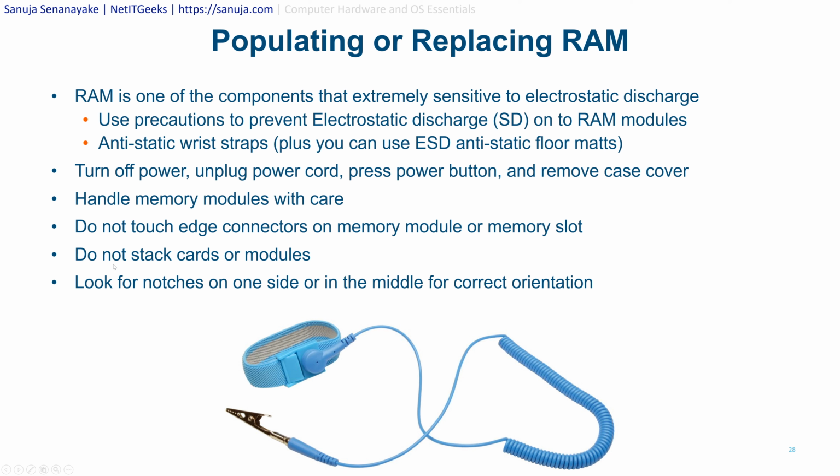I've seen even IT technicians with a lot of experience stack their modules on top of each other. That is a bad idea. It's okay maybe if you have something in between each of those modules, like some kind of anti-static paper, foam, or something like that. But other than that, do not stack them on top of each other.